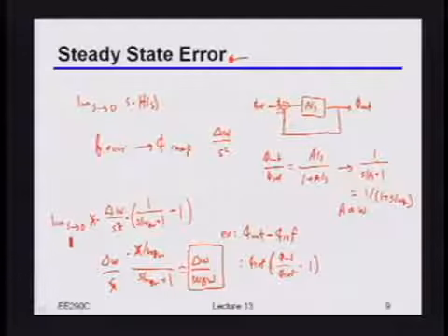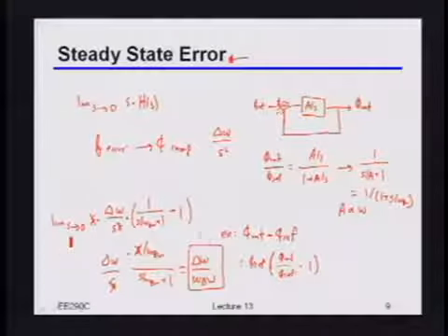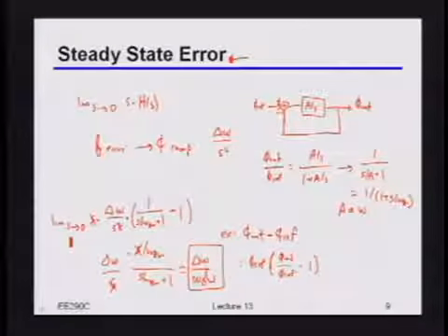So in other words, what this tells you is if you put that ramp into the first order system, that first order CDR, then what's going to happen is you're going to end up with a static phase error that's basically proportional to the rate of that ramp relative to the bandwidth of your loop.